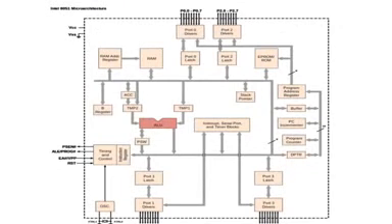So the serial port is nothing but, generally before knowing this, we have seen that you have 4 ports. These 4 ports are input output bidirectional ports, which you can also call parallel ports, because all 8 bits of whatever input we give are sent at a time.